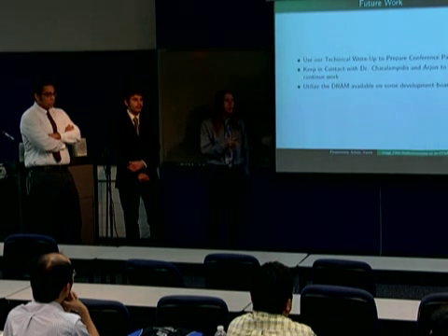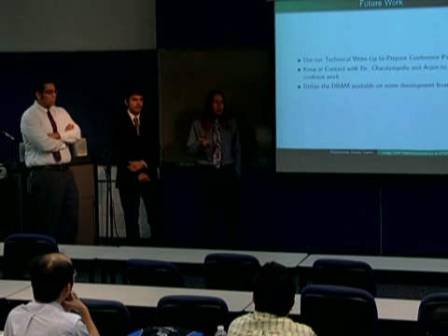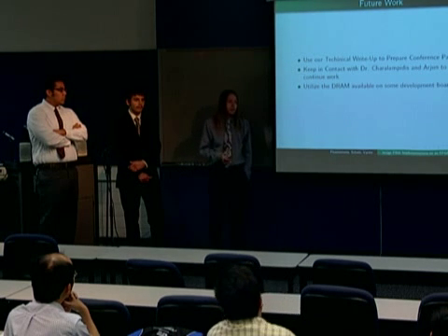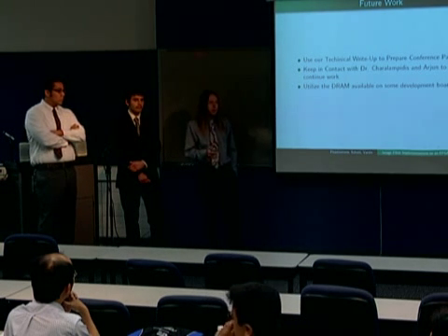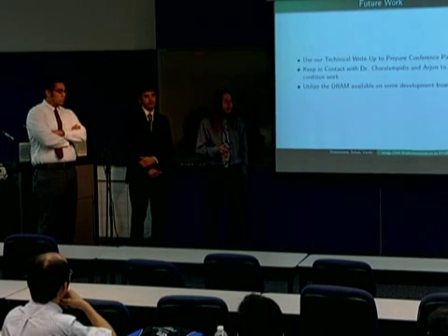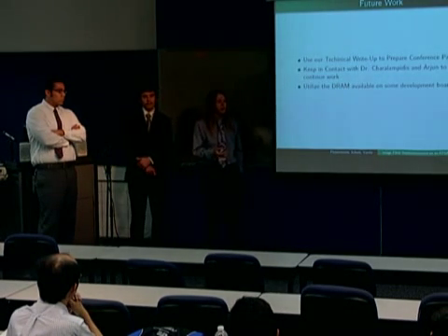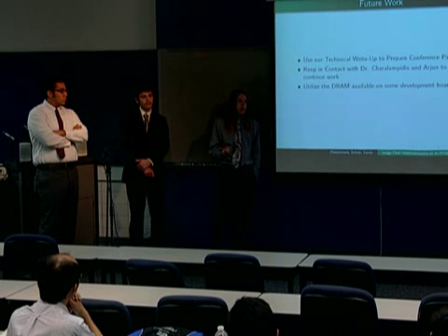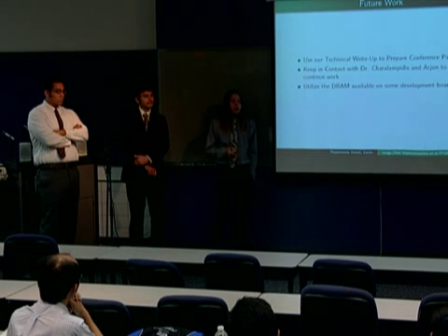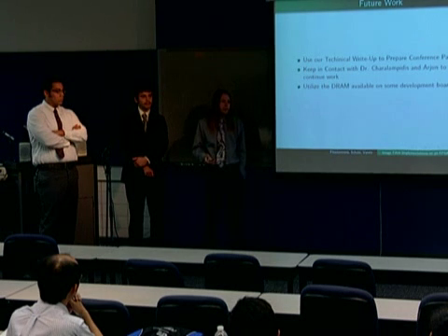Well, it wouldn't be just the image. It would be the size of the image combined with the size of the mask. It's so large that you can't store it on the FPGA to do the pipeline implementation. Then in that case, it would be preferable to do a non-pipeline because the non-pipeline doesn't use temporary memory. Well, it doesn't use lookup table and slice-based memory. It would use BRAMs, or you could also use DRAM, which has a lot larger available size. So the only reason you wouldn't want to use the pipeline is if you're dealing with images or masks that are too large for your target device.